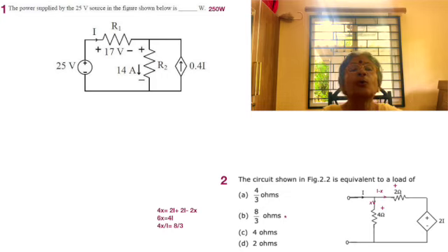When you get a dependent source, it immediately becomes obvious because there would be what are called rhombus kind of structures there. That rhombus structure will tell you that it's a dependent source, and whether it's a current source or a voltage source. If an arrow is shown, it's a current source, and if just the signs plus and minus are shown, it's a voltage source. But the value is very important, and that's where you need to focus.